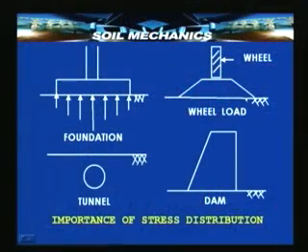Actually, it depends upon the relative stiffness of the foundation and the soil, and therefore, one needs to know the pattern of distribution before we venture into determining the distribution inside, within the depth of the soil. Another example is that of the wheel load. Let us take a look at this in detail.